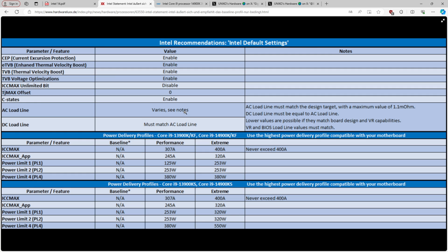You can't. So basically, Intel would have to take every single Z690, Z790 motherboard and measure, and at this point, if Intel's going to do that anyway, right, take the motherboards, measure the load lines on them, and then go tell the motherboard vendors, hey, you're setting it wrong. Why is this even customizable? Right? Why would you let them set this themselves when they're evidently not going to follow instructions?